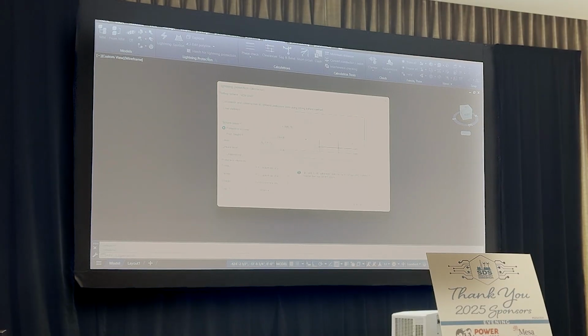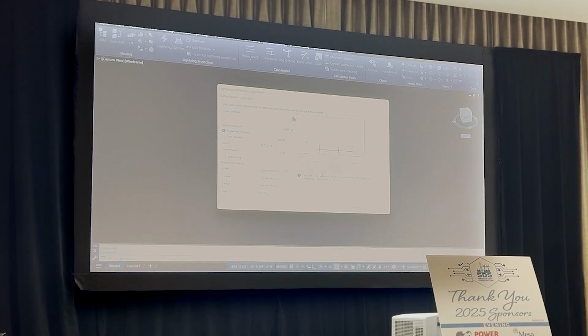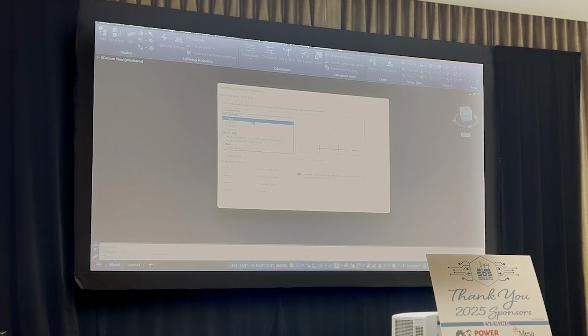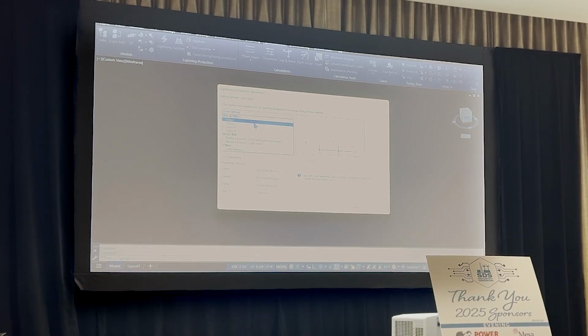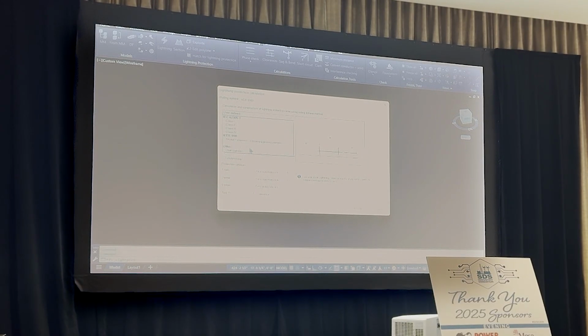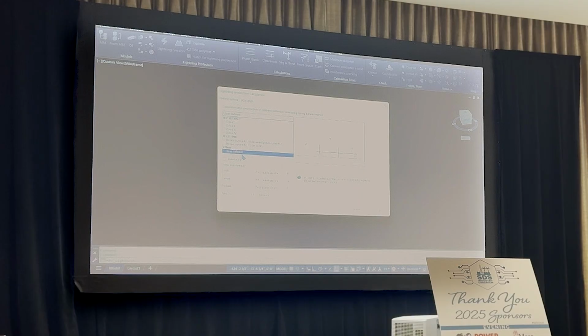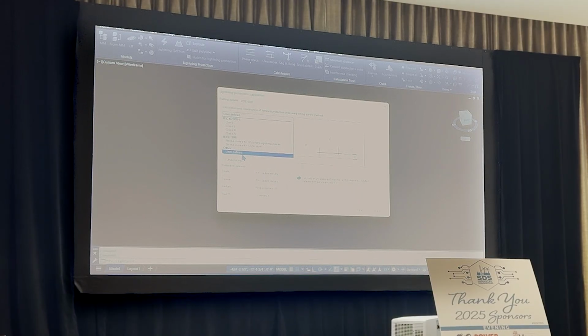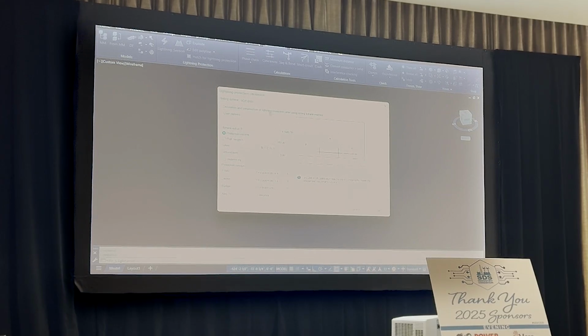And this one is pretty simple. So you have options for different standards you could run it by. There's IEC standards and IEEE. I'm going to use what most of us are probably familiar with, user defined, which means you define a sphere radius, and that's what you use. So I'm going to do user defined. I'll leave my sphere radius where I have it.